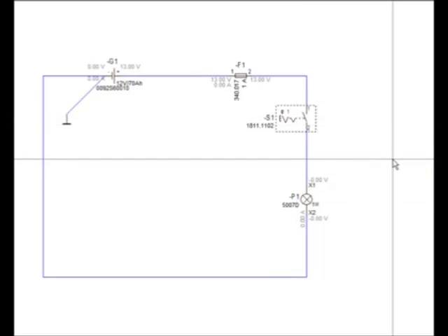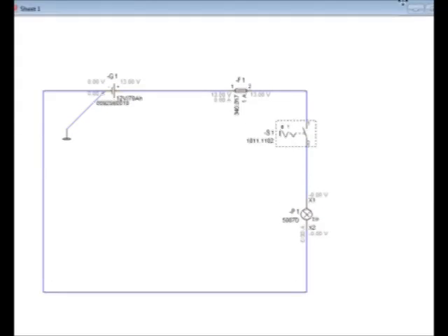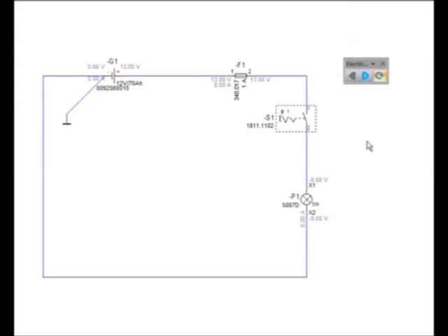We select this switch, and let's move these icons a little bit closer to the switch. They are the icons for the electrical checks. And here I can change the state of the switch. So it's closed now, the lamp is active, and it's open, and it's closed again. And you see the values for current and for voltage, they are changing, they are always actual.